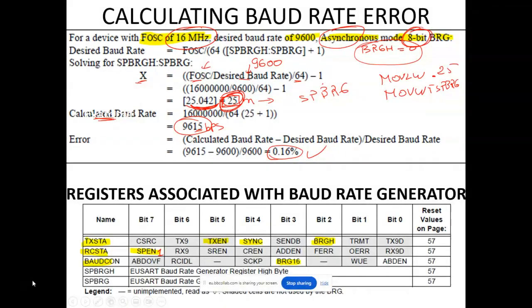Okay. And you have just here another bit, which is continuous reading enable. If you are reading data continuously, you are receiving byte after byte, byte after byte. In that case, the continuous reading enable should be 1. The rest here are errors or flags or configuration 8-bit, 9-bit. So generally you have 8-bit, so no need to use the TX9 or RX9. So the rest you can use 0 for them. Okay, so if we summarize, 3 bits for the configuration and these 2 bits for the baud rate, and then you can send and receive the data normally.